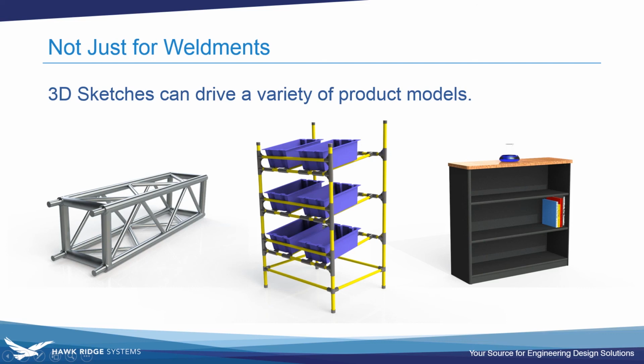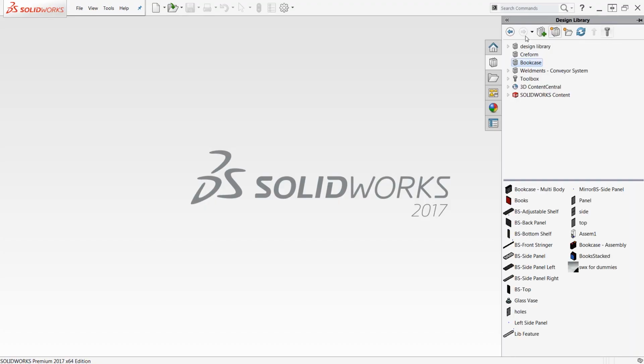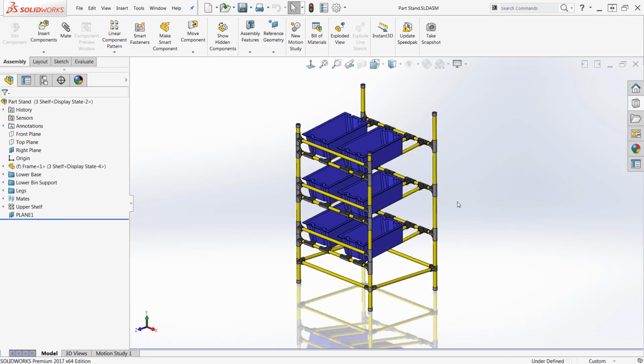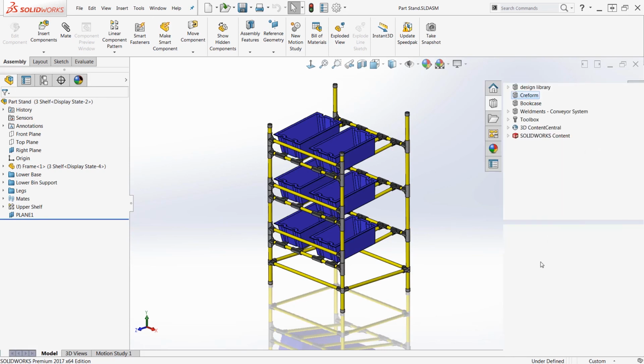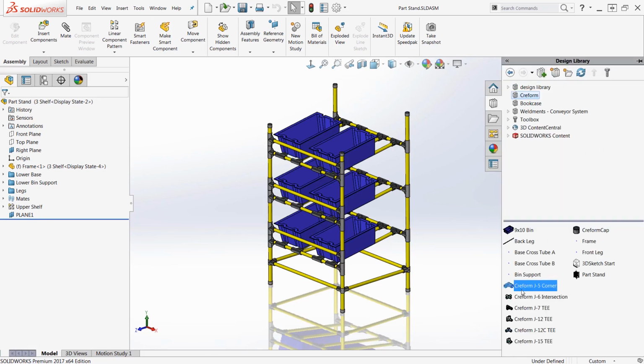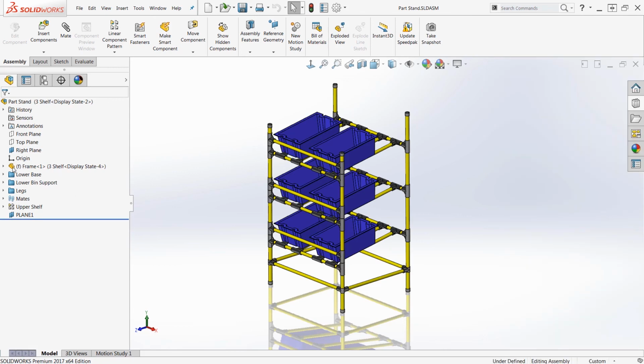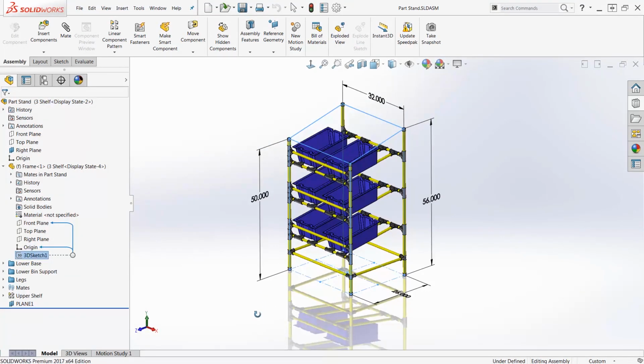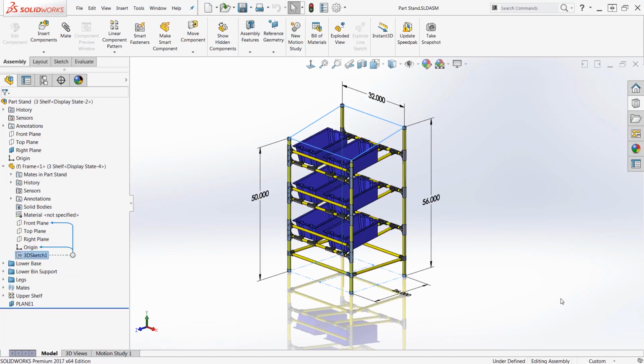I'm going to go back to my SolidWorks here. And in my design library, I've got a couple things, links to those project folders where those are located. And I'll just open up this stand here for you just to look at. And if we look at that again, I basically modeled up the plastic connectors. With this one, I created a part that has a single 3D sketch in it. Those are the only dimensions in this model. Changing these 4 dimensions changes the overall size of this.